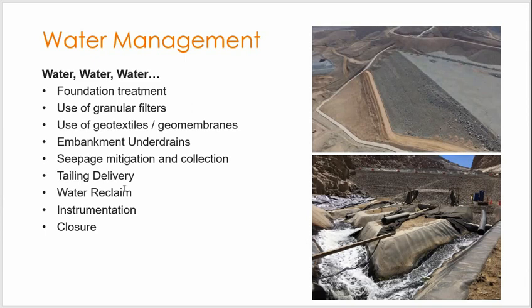Just a couple more items here. I wanted to touch on instrumentation, which is a big part of it. Installing piezometers within your dam and within your foundation to monitor your pore pressure conditions and make sure you're not getting elevated pore water pressures. You're not getting rises in your phreatic surface that could potentially cause dam safety issues down the road.